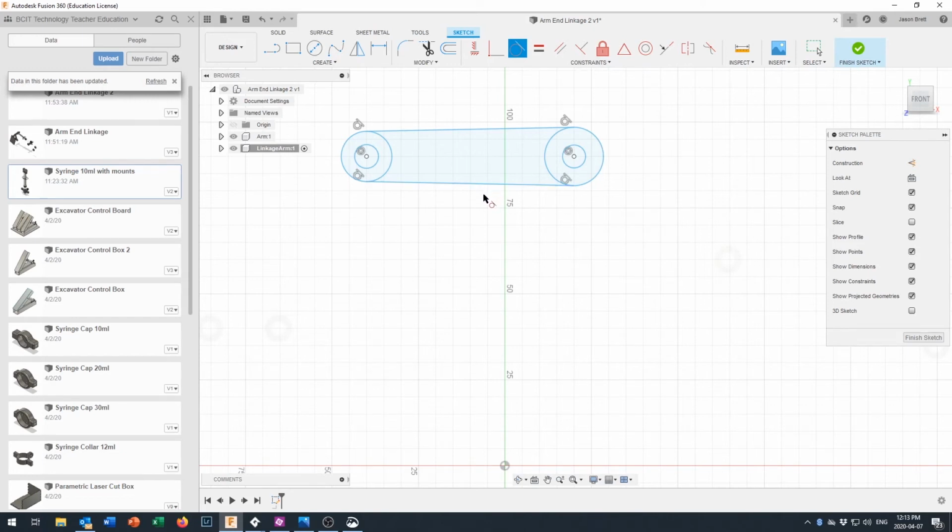If you've got that, you're just going to need to hit escape, find that constraint, highlight that constraint, and delete it. Okay, so right now we're pretty good. Now we're just going to bring in some dimensions right here, and this one right here is going to be hole inside diameter.